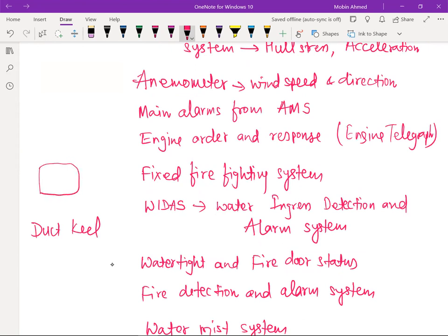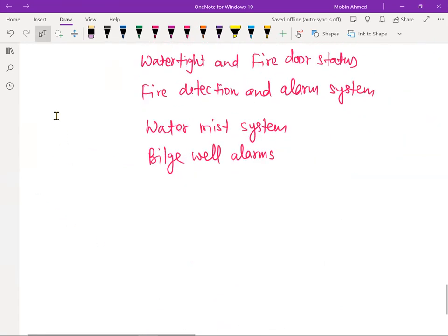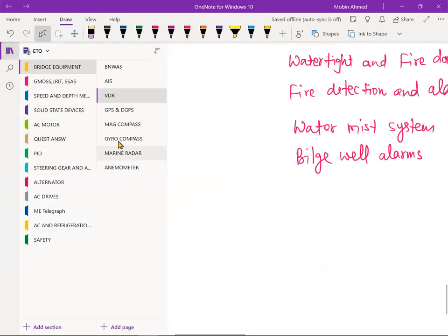Yeah, a door is there. In that there is an indication. There is a micro switch, and this indication goes to the bridge also. So like this, if any hull opening is there anywhere, that is the important one. There is an indication that will be going. So all these are going to be recorded.